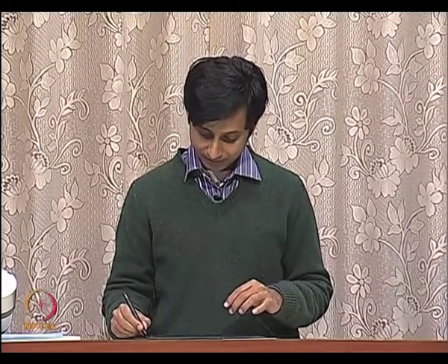All right. So, you are going to burn man hours, you are going to burn power in the sigma delta modulator, area and power in the sigma delta modulator, and you are going to divide by a fraction. Dividing by a fraction is going to allow you to have larger loop bandwidth. Larger loop bandwidth will allow you to have faster settling time, it will allow you to have better phase noise, unless you have dirtied the phase noise with your sigma delta modulator.